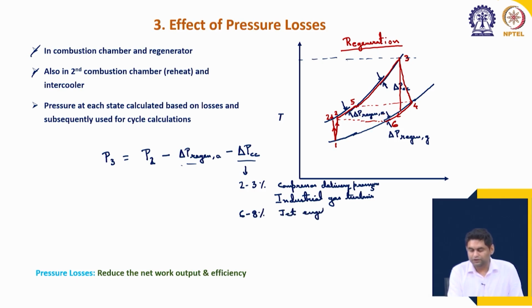Why? Because in jet engines the air intake occurs at a high velocity. So, we do not reduce the velocity as much, and as a result holding the flame is more difficult. Industrial gas turbines are stationary, while jet engines are moving with high velocity.